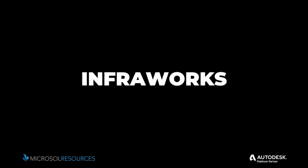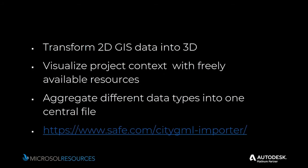Now, as you saw, I was able to bring that information into Map 3D quite easily. Unfortunately, because of the limitations of the data type, GIS information tends to be two-dimensional, right? So points, lines, polygons, and raster images. So what if I want to be able to take that and make it 3D? Well, Infraworks excels in that, and even though it's used primarily as an infrastructure transportation conceptualization application, you can easily take any GIS information that's available and stylize it and view it in 3D.